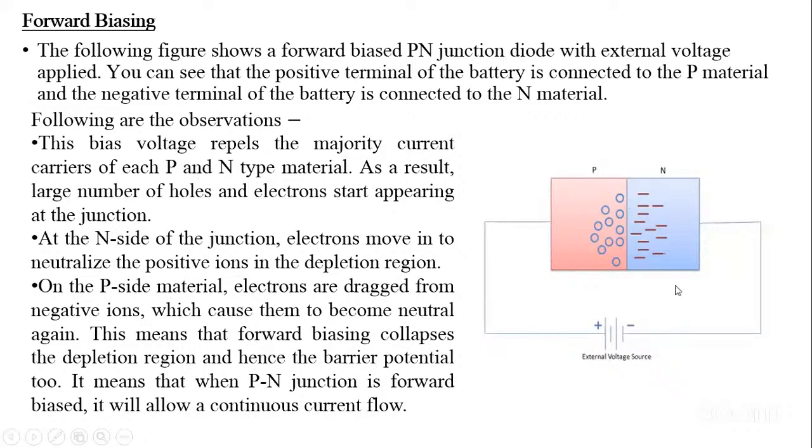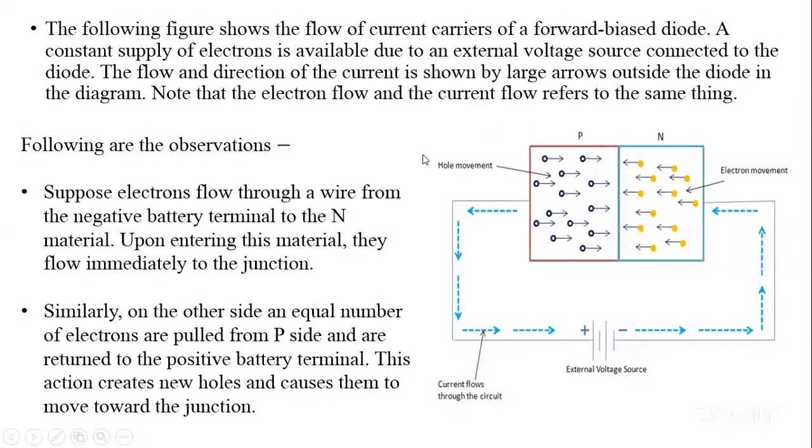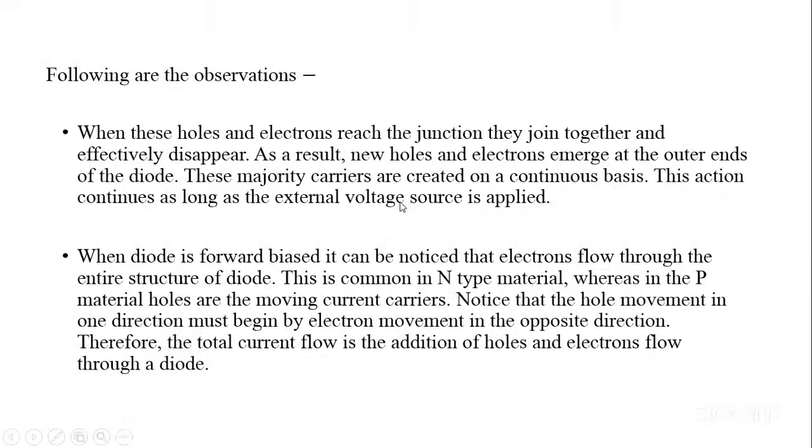Similarly, the electrons on the other side are also pushed back by force of repulsion, and they are all beside the junction. So with this, electrons can continue to recombine with holes. So that is what positive forward biasing does. In that process, current will begin to flow across the junction. You read the rest, I've explained it.